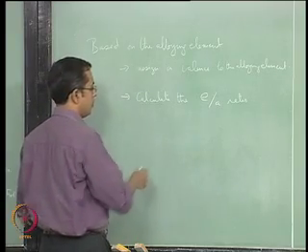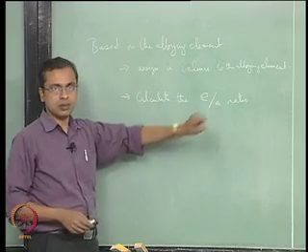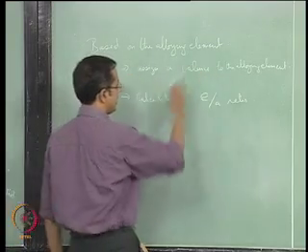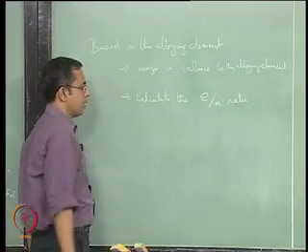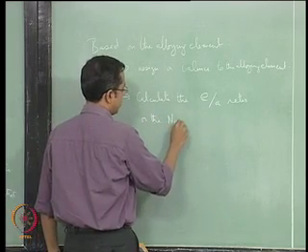So you calculate the E by A ratio, and this is on a per atom basis. So we can assign a valency to the alloying element and we can calculate the E by A ratio, or the number of valence electrons per atom.